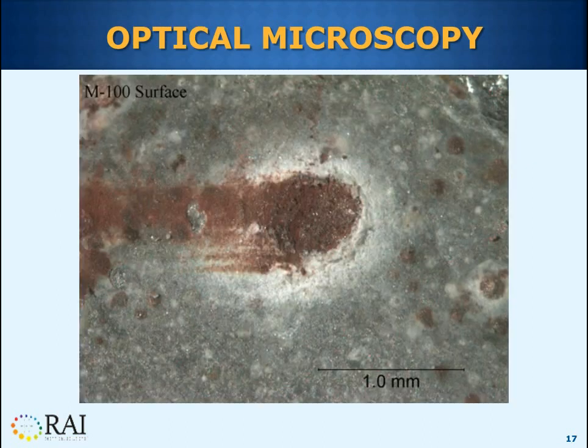This is an example from my work using an optical microscope. This is a surface view, about 40x magnification, of a lead coating applied to copper sheet. The coating corroded in spots. The red corrosion spot shown was caused by a pore in the lead coating and is about 0.5 millimeter in diameter. Certain lead corrosion products are red.